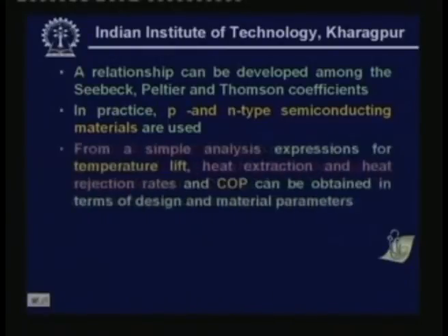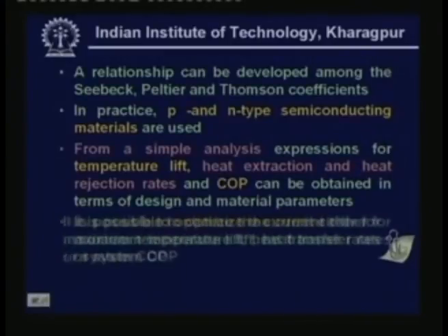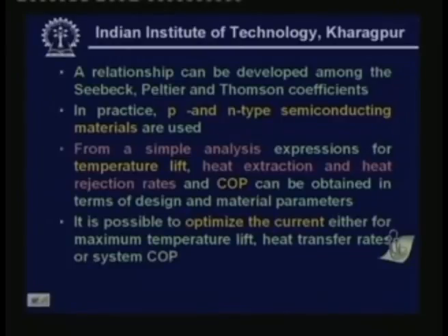systems. And from a simple analysis we can derive expressions for temperature lift, heat extraction and heat rejection rates and COP, in terms of the design and material parameters. And it is also possible to optimize the current either for maximum temperature lift or for maximum heat transfer rates or for maximum system COP.